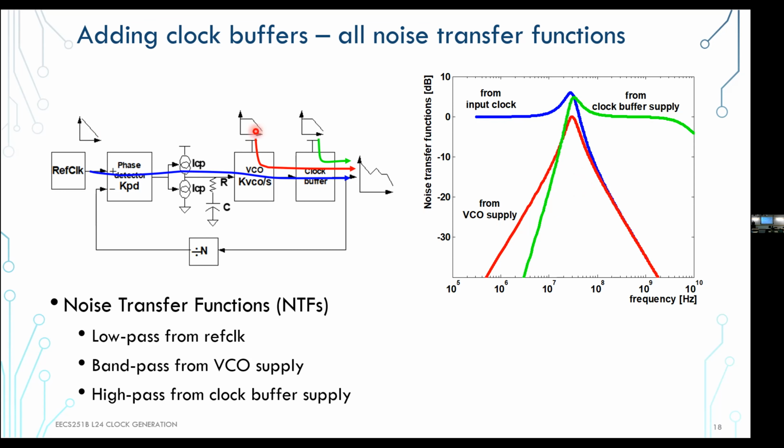The supply noise, you can kind of think it's low pass. It has to end at some frequency, but depending on the digital system, you'll have a highly non-white spectrum. First of all, you will have a lot of spurs at the clock and multiples of the clock, because a lot of registers are transitioning at the same time. So your supply noise signature looks very bursty. And then there's a little white noise, depending on the logic depth of each stage as the logic is transitioning.